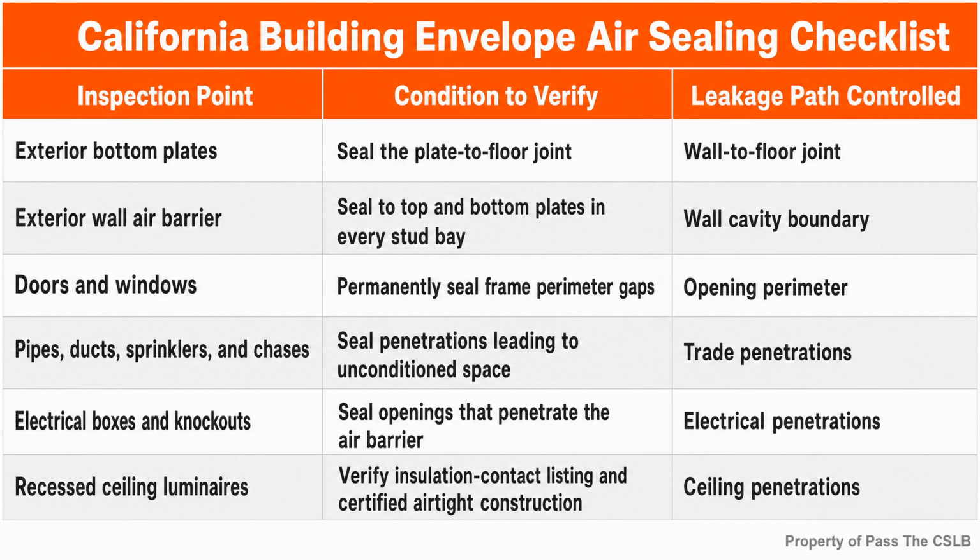The first supervisory decision is identifying where the boundary actually runs. The building envelope consists of the components that enclose conditioned space and separate it from unconditioned space or the outdoor environment. On a straightforward house, that may include exterior walls, the ceiling under a ventilated attic, and the floor above a crawl space. A wall separating living space from a garage can also be part of that boundary. On a more complicated project, the line may turn through roof assemblies, floors, cantilevers, shafts, or demising construction. I do not assume that the boundary follows the easiest path for a crew. I follow the approved project documents and the applicable energy compliance information.